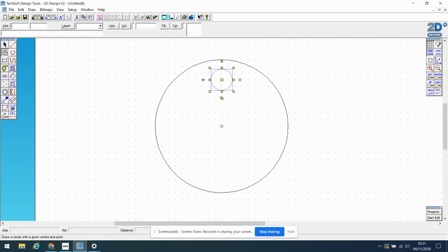Another thing I did try and show my group was the positioning of a cutout for the spoke. This is going to be a cutout where the material is going to be removed, so the spoke will actually be the bit next to it. So if I drew a smaller circle underneath and I got my line tool, I put step lock on a moment, drag that down to there, and drag that down to there.